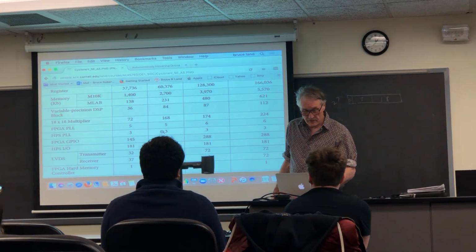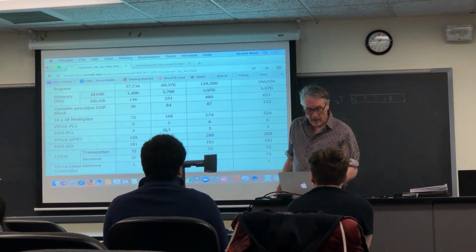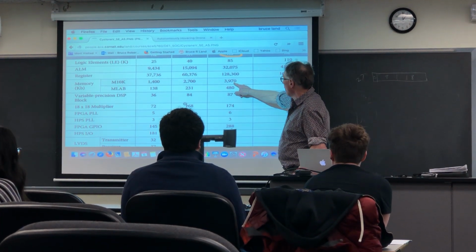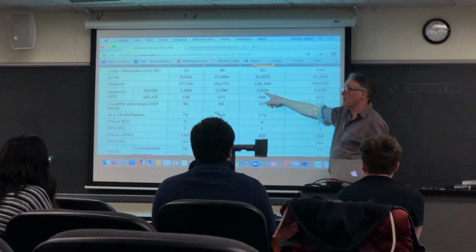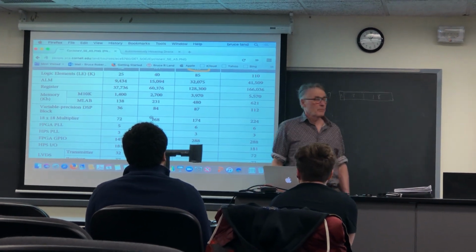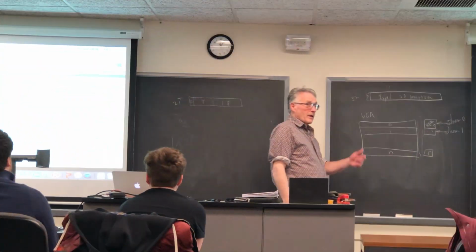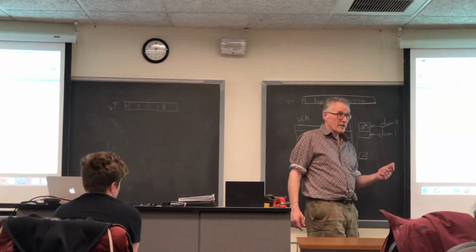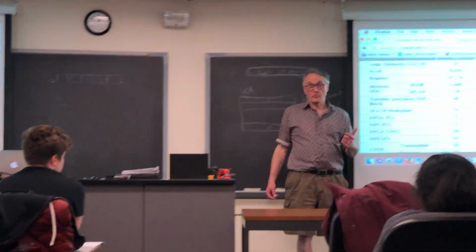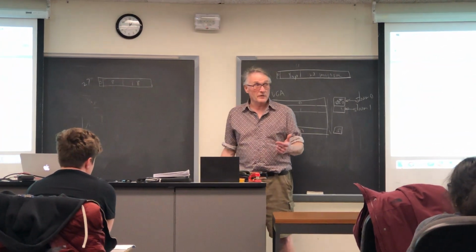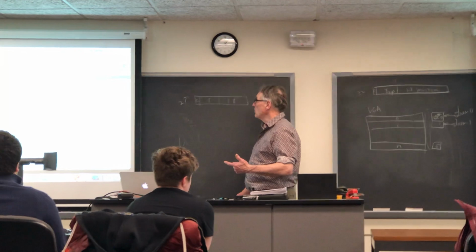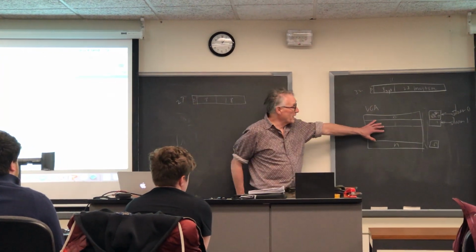302,700 pixels on the display. And we have, in memory, about 4 megabits of M10K block. 4 megabits is about half a megabyte, so 500 kilobytes, which is enough to, so if you use 60% of internal memory, you have enough memory to completely describe the VGA image.